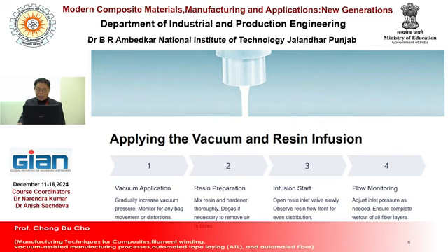And infusion start. So open the resin inlet valve slowly. So observe the resin flow front for even distance. This is very common sense, but we don't know how slowly the valve should be opened or closed.